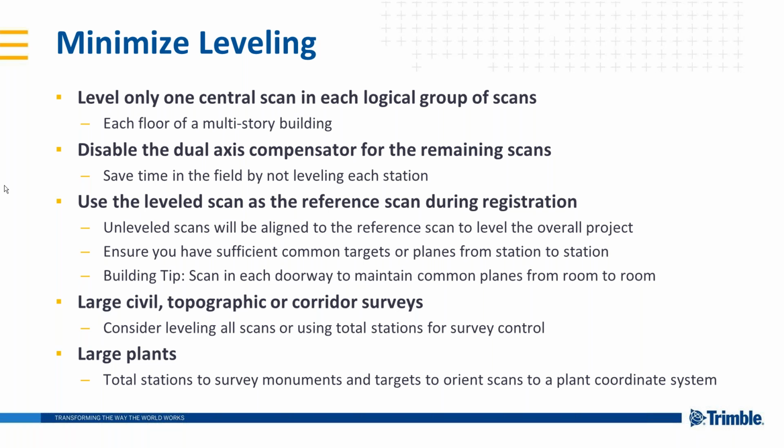In general, leveling depends on your application and your workflow. It doesn't hurt to keep all stations level with the dual axis compensator enabled, but minimizing leveling can improve productivity in the field and simplify workflows when it's not required.